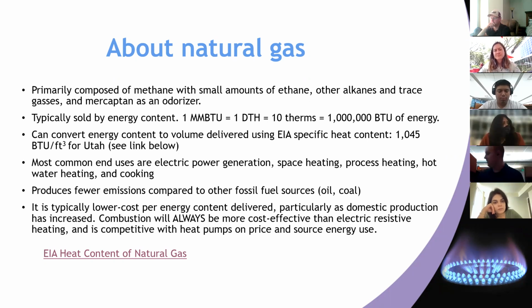Basically, if you're trying to do heating, natural gas is usually the least expensive way to do it. If you're looking at an electric resistance heater, it's 100% efficient at converting electricity to heat, but you're still going through intermediate conversion steps to get gas to electricity back to heat if that electricity is generated in a gas-fired plant somewhere.